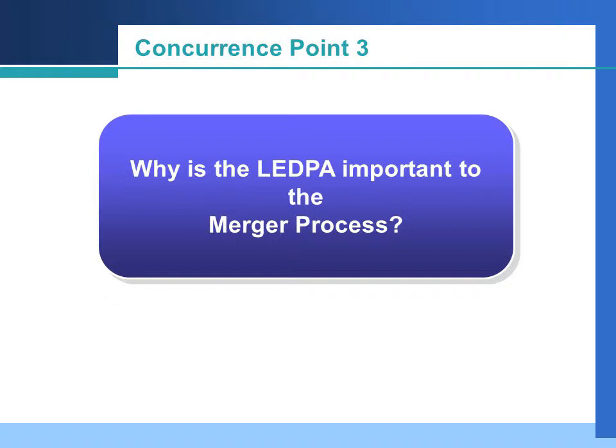Under Section 404 of the Clean Water Act, for any proposed action that may affect waters of the U.S. and is not water dependent, there is a presumption that there is an alternative that has lesser aquatic impacts, informally known as the high ground or avoidance alternative. Considering this, the alternative that can be permitted is the one with the least impacts that is also considered to be practicable. So the project team is obligated to select a LEDPA that meets avoidance and minimization criteria for subsequent issuance of permits prior to construction.